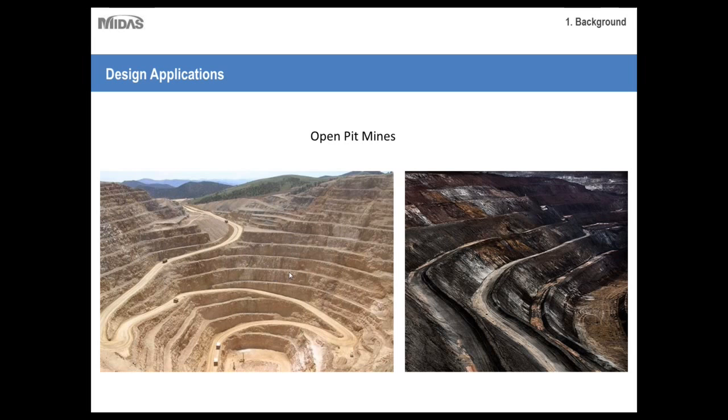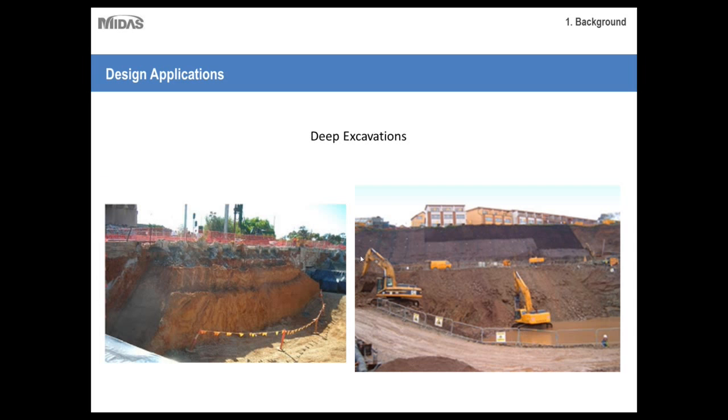But there are some instances where additional ground supports are required, such as rock bolts, cable bolts, and shotcrete. Also, dewatering bores may be used to relieve water pressure by drilling horizontally into these walls, since water pressure is often enough to cause failures in the wall by itself. So even though rock slopes are naturally much more stable than soil slopes, there are still various things to consider, and there are still instances when structural reinforcements might be needed, especially for open pit mines, which consist of several layers of slopes.